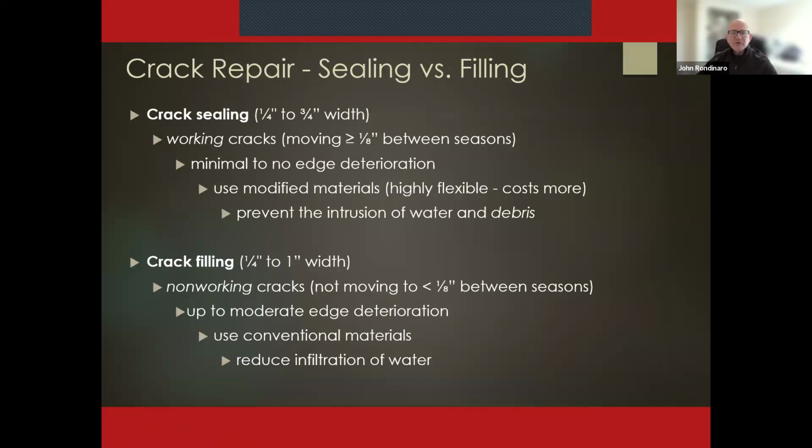In terms of sealing versus filling, there is a clear distinction. When you're sealing cracks, you're addressing your working cracks, which means they're moving greater than an eighth of an inch between the seasons. When you're filling cracks, those are your non-working cracks. They're not moving, so you can use a lesser material to fill them. And this is what a crack should look like. This is a perfect candidate for crack sealing.